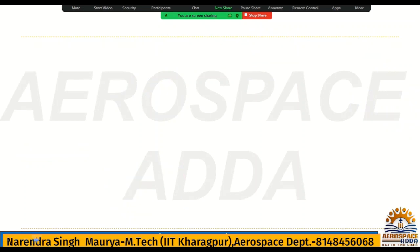So generally, convergent nozzles, I told you, are for subsonic flow, hence convergent nozzles are used in almost all present subsonic transport aircraft. Moreover, in most cases these convergent nozzles are also choked, when the Mach number reaches 1 at the exit, and incomplete expansion of the flowing gases to the ambient pressure is encountered. At nozzle outlet, the gases exit at sonic speed while the pressure is greater than ambient pressure.